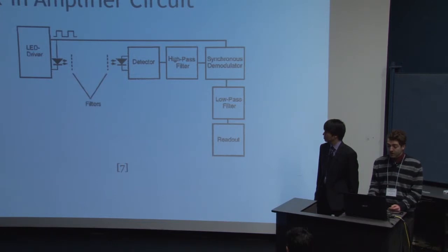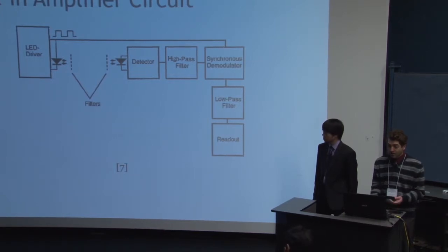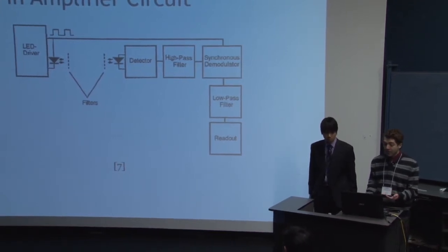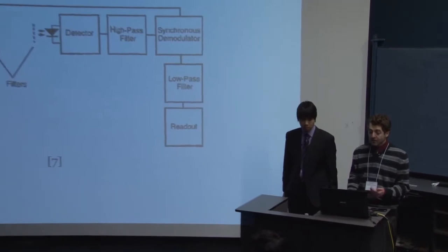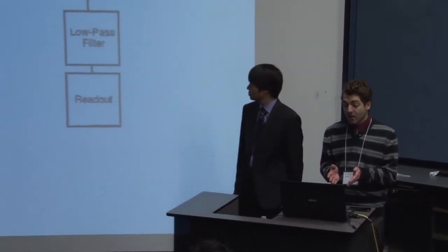And finally, this is coupled with our known carrier signal, which is that of the LED, and processed by a synchronous demodulator. This is our final useful signal, which is then passed through a low-pass filter, effectively completing a narrow bandpass around the frequency of importance to us. And this is finally amplified by a typical operational amplifier, and the output is read.